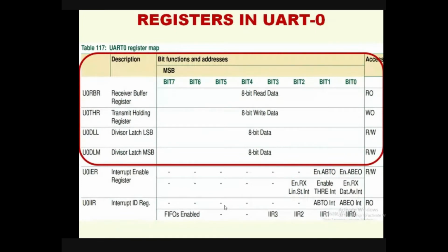And these are all the registers associated with the LPC2148 microcontroller's UART, that is Universal Asynchronous Receiver Transmitter. We are interested in UART 0. There is a register called UART 0 receive buffer register. There is a register called UART 0 transmit hold register. There are the UART 0 divisor latch LSB and divisor latch MSB registers. Through these divisor latch registers, we will fix the baud rate.